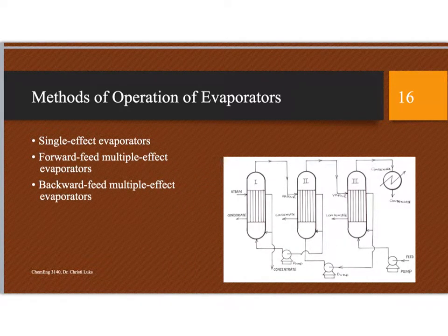These also can be a backward feed, so this one's a little bit more complicated to first look at, but I'm going to bring in my process fluid. So notice my feed is over here on this side. So I'm going to bring this in to the first evaporator, and I'm going to have steam heat this, and I will have some liquid that comes off the top.